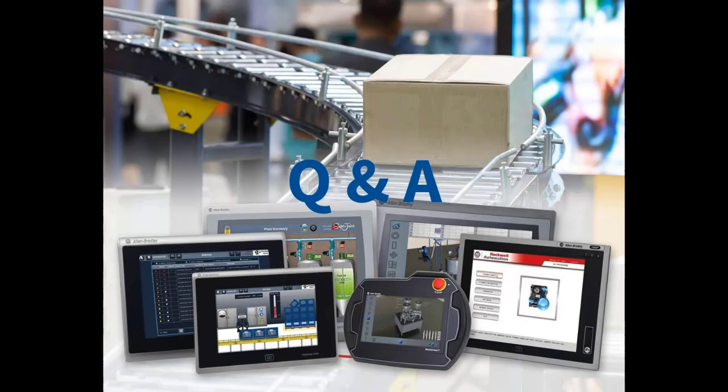And a couple more for you, Eric. Will I need to download the firmware from the website, or will it install when I install the latest and greatest FactoryTalk View Studio? So the Series B starts out at firmware 12, and since FactoryTalk View Studio version 12 has been out for quite some time, that firmware will not be on your computer. So you'll have to go get it initially from the website.